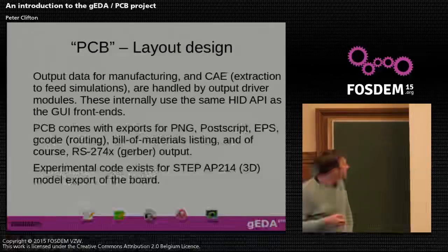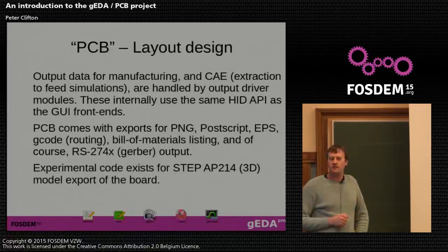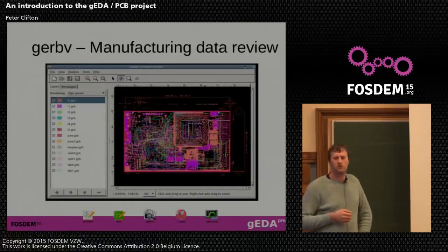gerbv, I believe, is quite extensively used. It's got complete support for the RS274X standard, and I believe it's faithful to that standard. So if gerbv says it looks like this particular picture on screen, that should be what your manufacturer produces, and you have a reasonable degree of confidence that's going to be the case.